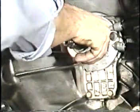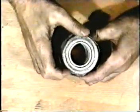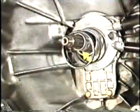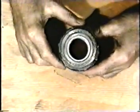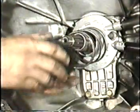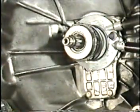To test the release bearing, first remove it from the slave cylinder. Rotate the bearing while putting slight pressure on the outer race. It should turn smoothly. Check the inside of the bearing and the input shaft quill where it rides for burrs. The quill is smooth, but there's some minor roughness on the inside surface of the bearing. In this case, either polishing or replacing the bearing would be acceptable. Of course, if there is extensive damage to the inside of the bearing, it should always be replaced.